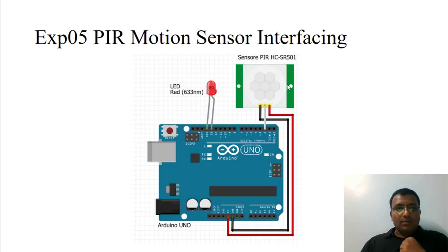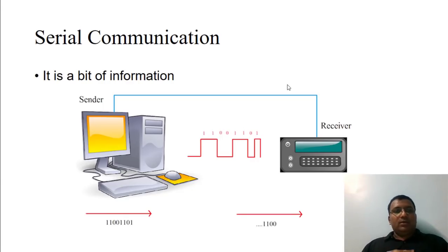Okay. Next, serial communication. Serial communication is a very important point, because we need to communicate different devices with the microcontroller by using serial means. Serial is very popular because it requires very little hardware, and we can have acknowledgement over the serial lines as well. There are different serial protocols, like UART, Universal Asynchronous Receiver Transmitter, I2C as the inter-integrated circuit bus, SPI, serial peripheral interface, SSP, Modbus, and CAN, controller area network. So many serial protocols are there.